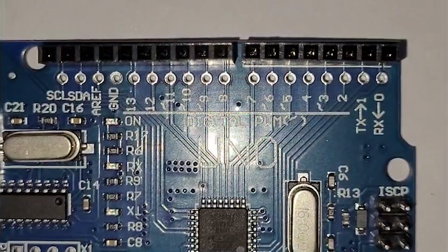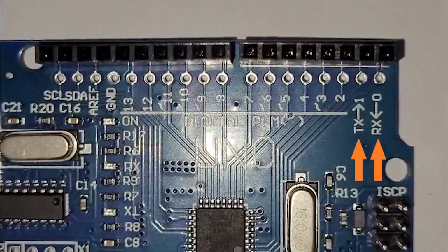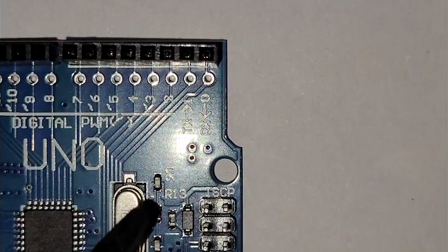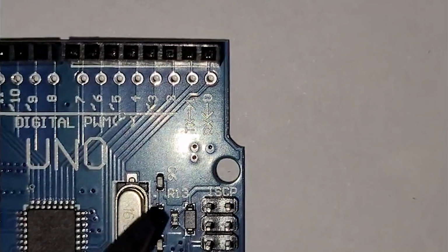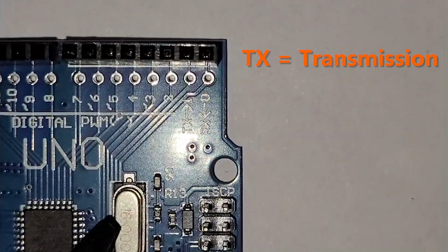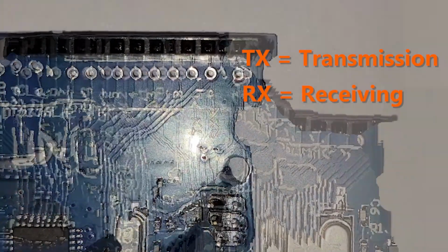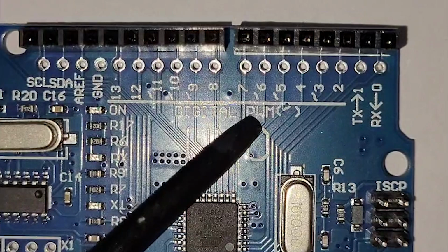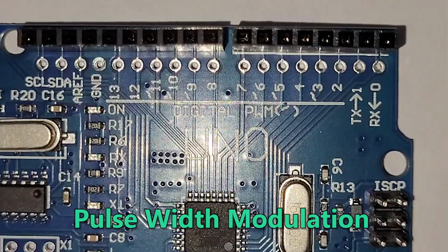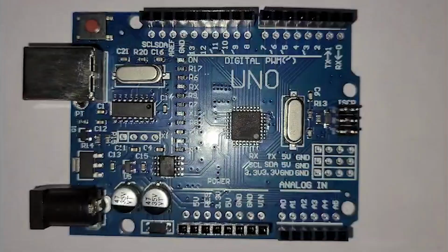Now, if you give a close look at the 0 and 1 pin, you will see that they have special symbols. They are used for communication with the USB port, TX for transmission and RX for receiving. Some pins have a squiggly line. These are called pulse width modulation pins or PWM pins. These are capable of turning voltage high and low at different frequencies.